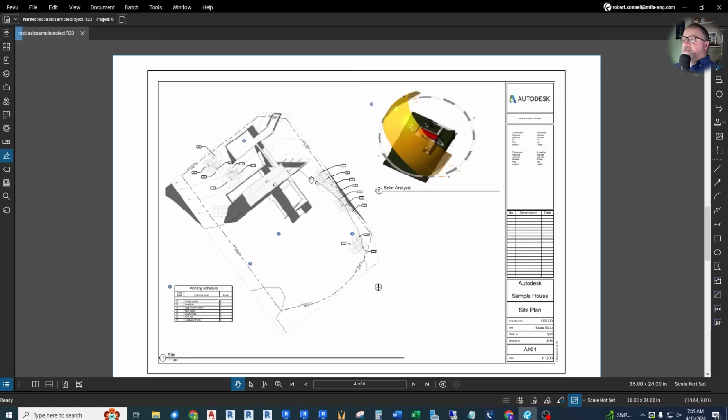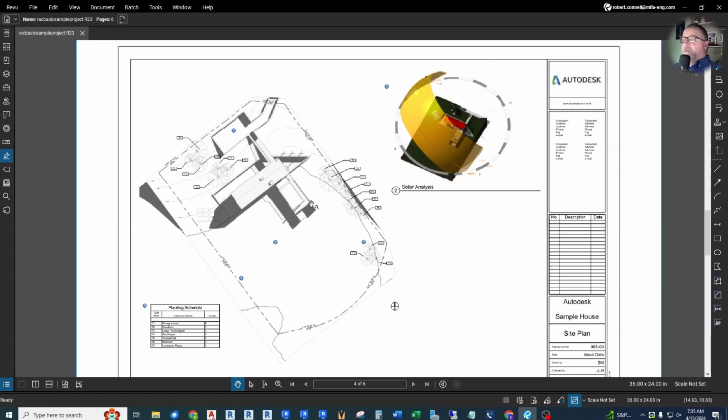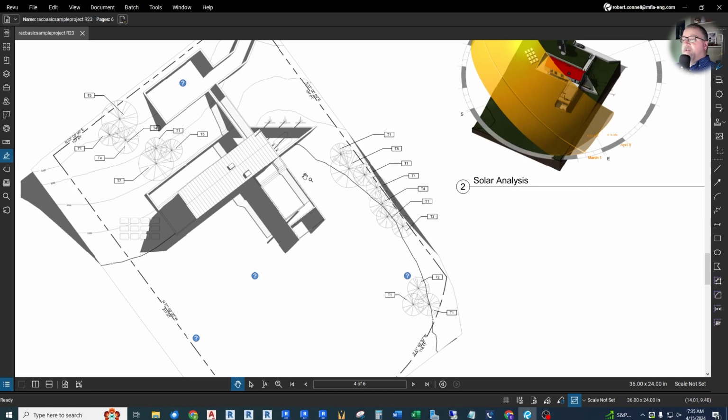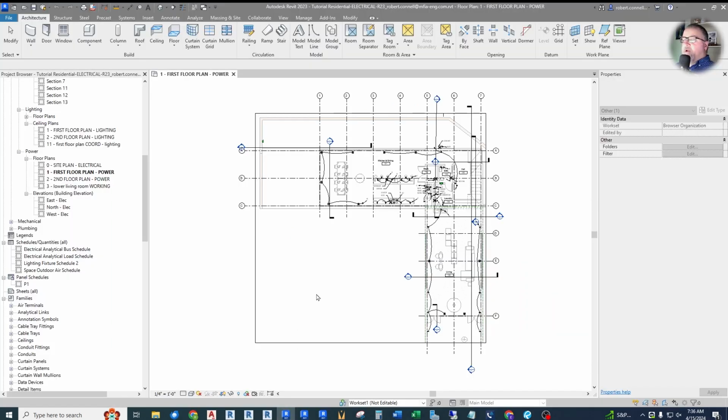And in the previous video, to create our site plan, I showed a method of bringing this PDF into our model and acquiring with just lines and angles what angle this is tilted at and setting things up that way. But like the viewer pointed out, if the architectural model is set up properly, we can acquire that angle directly from the architectural model and set our site plan up for that without having to go through this PDF scenario.